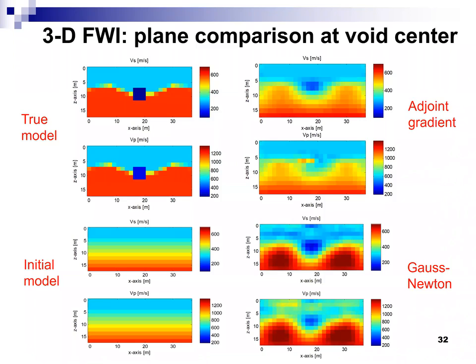Now, if we can recommend the anomaly location, it's still helpful, right? For a large area, we tell them to do only 3 CPT, it's still good, right? So we can still save some money. But we cannot distinguish the void from low velocity soil. Void or soft material is difficult to identify from adjoint gradient. But with Gauss-Newton, you can see this one go less than 100 meters per second, very clearly.